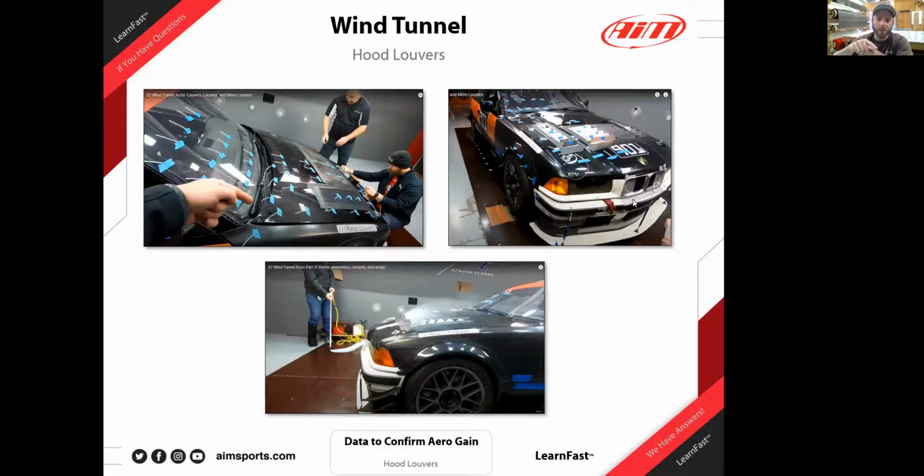And like I mentioned earlier, underneath the wind tunnel, you can run pressure probes to pretty much whatever you want, but Al ended up running them to the front of the radiator and the rear, and you can get a pressure drop across to know how much of a gain you would get in basically cooling capacity. So yeah, tons of data on louvers and stuff, and they're pretty neat devices for sure.